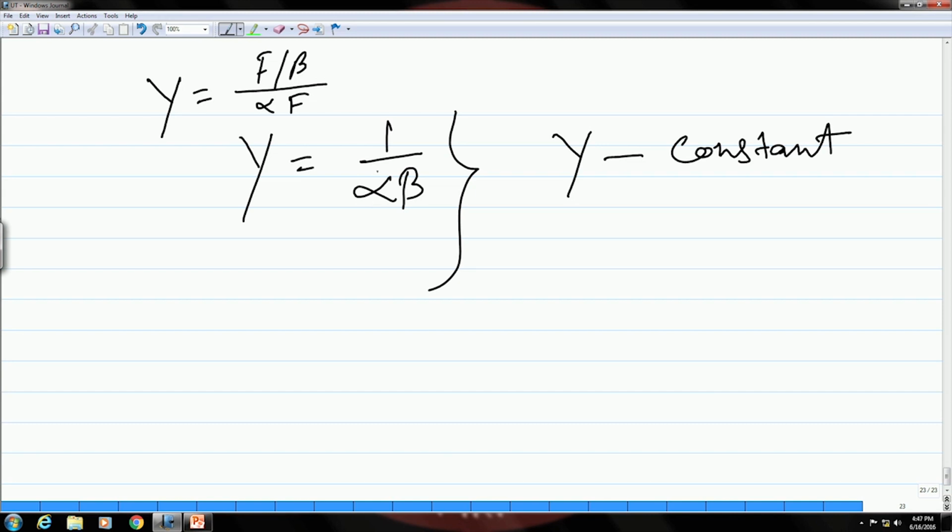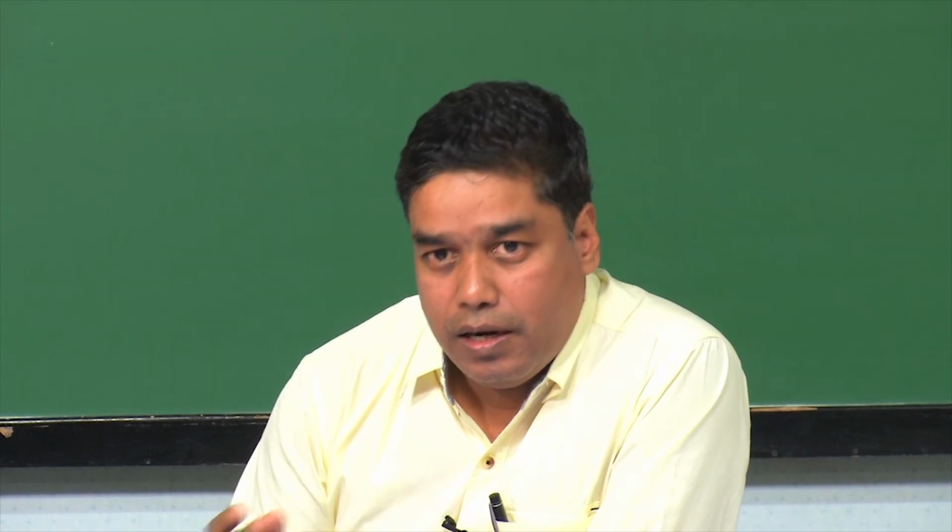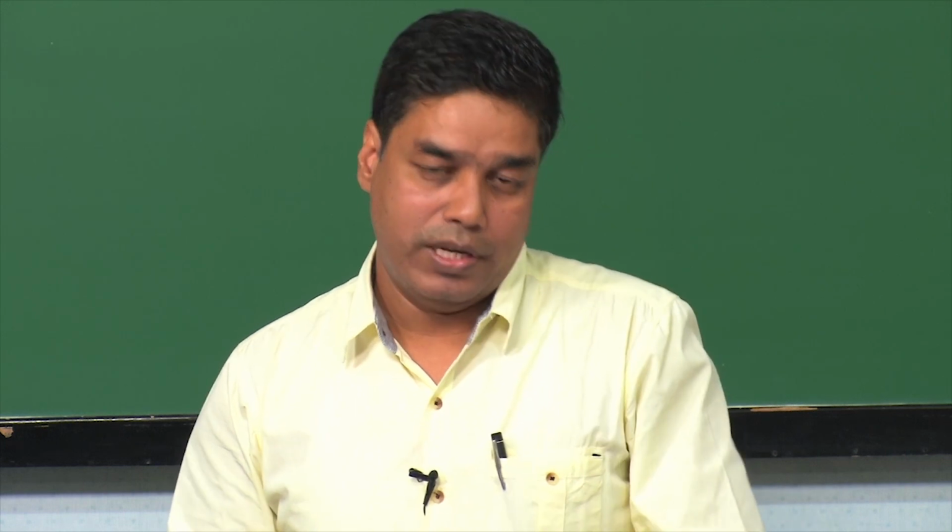Okay. So, if you increase alpha, for example, then beta has to be reduced, because this has to be kept constant. Okay. So, that is why it is not possible to optimize both alpha and beta together simultaneously in one transducer. So, you either have to compromise with the receiving ability, or you have to compromise with the transmission ability. But for the commonly used materials, for the commonly used piezoelectric materials, the values that you have for alpha and beta are enough for both transmitting and receiving.